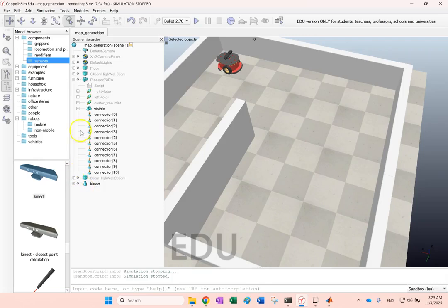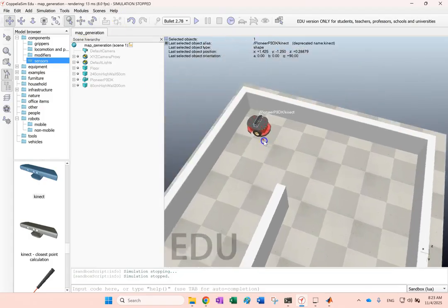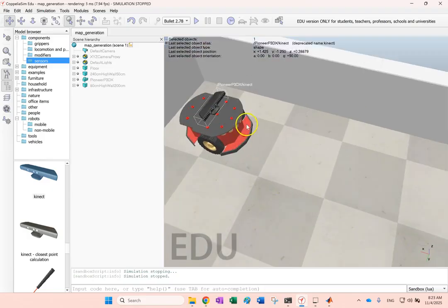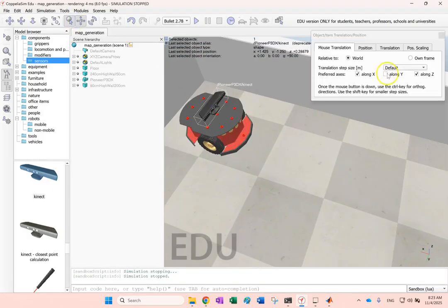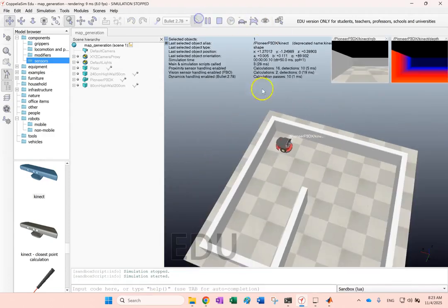So one thing you want to do first is make sure that the Kinect does actually belong to the robot, so it moves with it. And as I showed you, you need to bring the Kinect forward so it doesn't see anything from the body of the robot, only sees everything from the basically the scene, something like this. Bring it this close. So now look, when you run it, if you look at the depth, you should only see the depth from the environment.